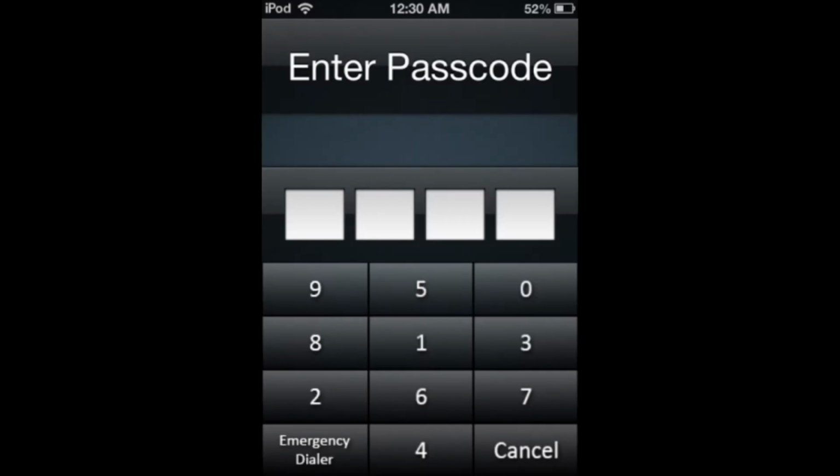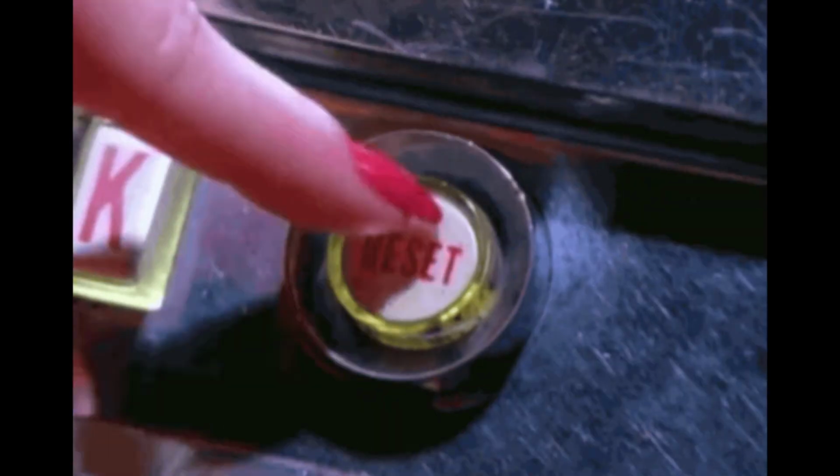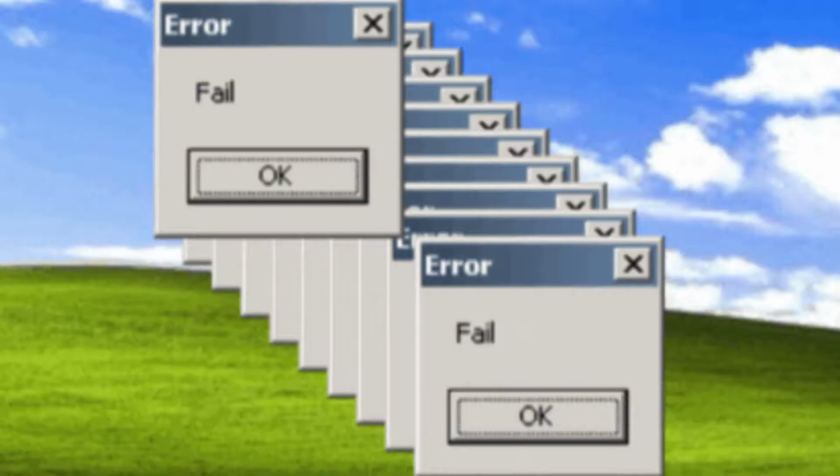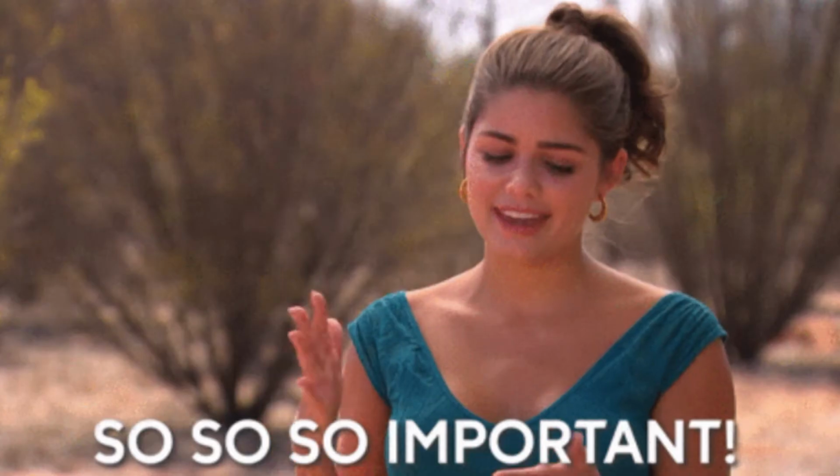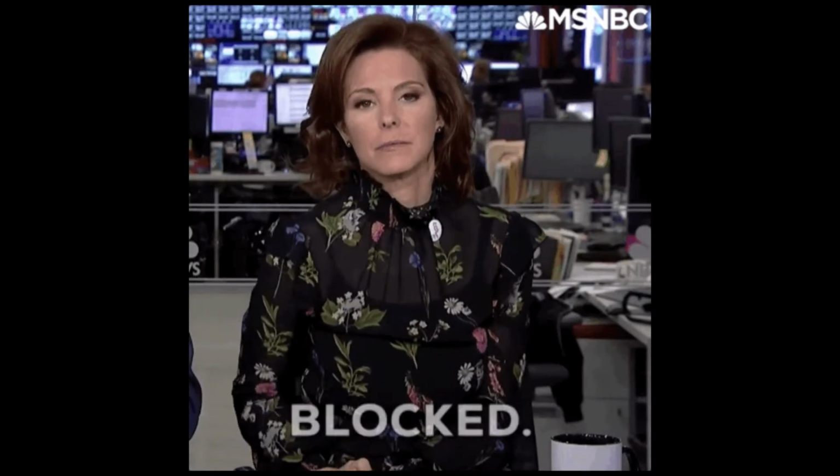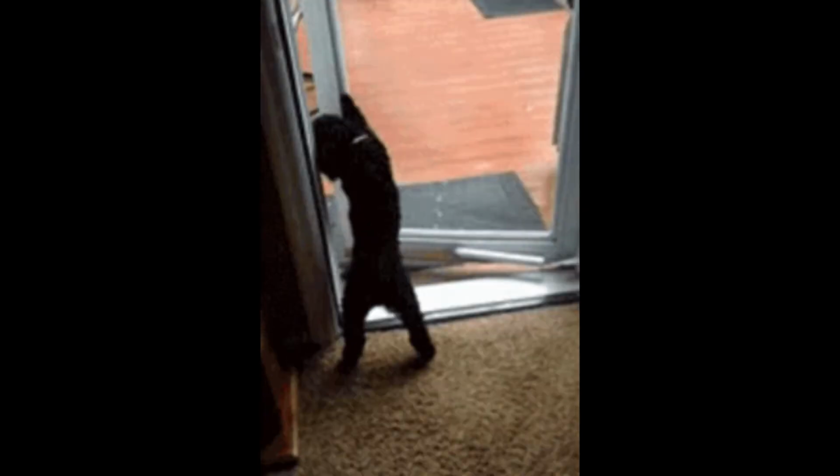Now, what are the requirements? This device should set a 4-digit password and save it until a reset button is pressed. It should also mark an error when the password is incorrect. We should show the digits when those are typed in a display, and a keyboard that includes the digits from 0 to 9. Also, and most importantly, this device must block itself when the person types the wrong password and unblock itself when the person types the correct password.